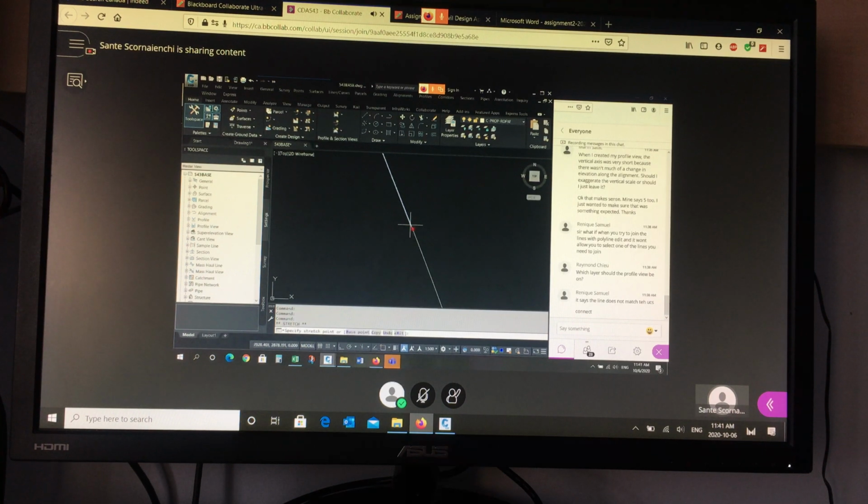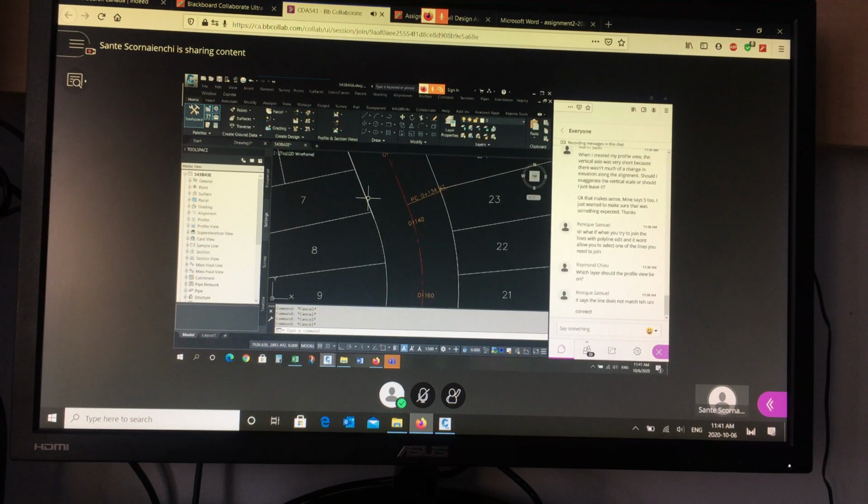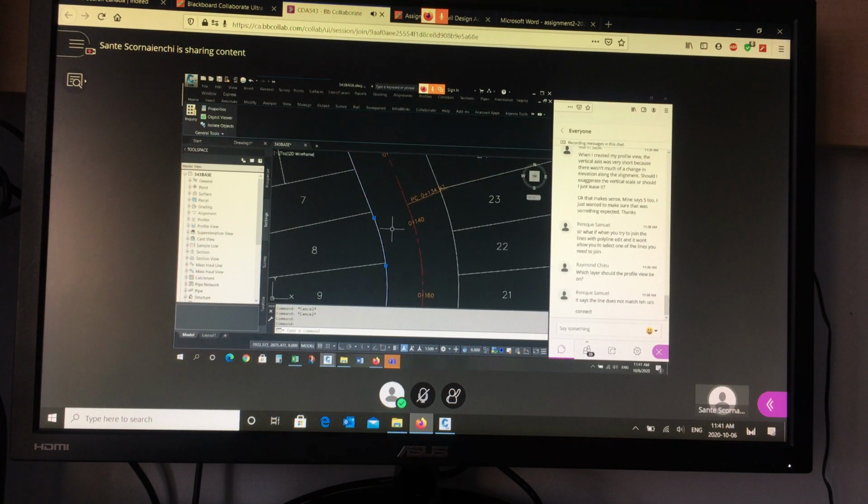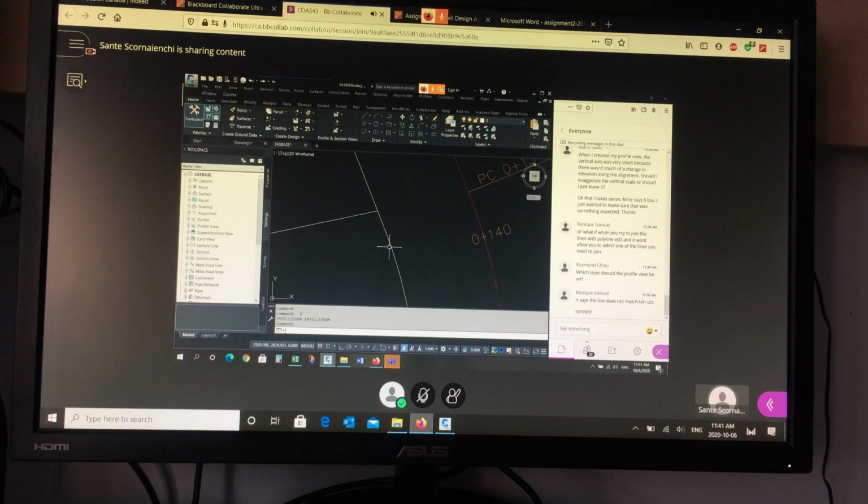If it's ever so small, maybe the distance is in the 10th decimal place. If you click on one and you click on the other, it looks like it's the same spot. When you click onto one and you move it and the other one doesn't go with it, that means the coordinates weren't exactly the same. So that's another kind of test you can perform ahead of time.